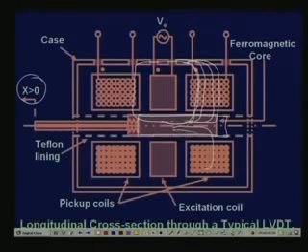When it returns, since these parts are non-magnetic, the overall reluctance of the path is limited to these air gaps, but if it has to come through this other path, then it has to go through this much of air gap. So the flux will not prefer such paths, and therefore it will not link the second coil.